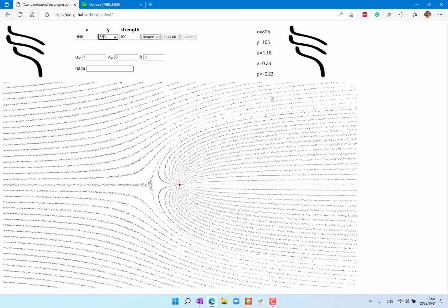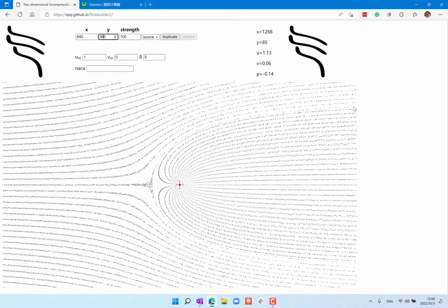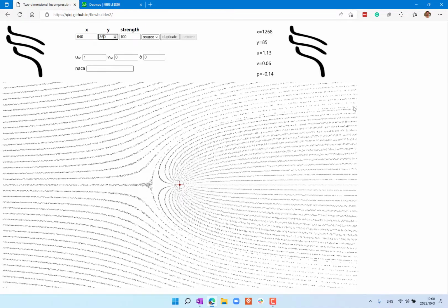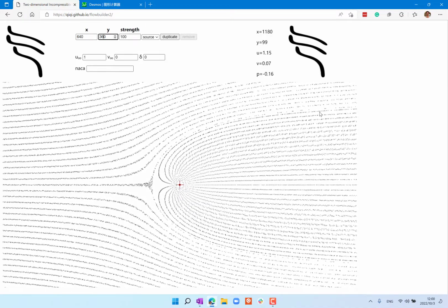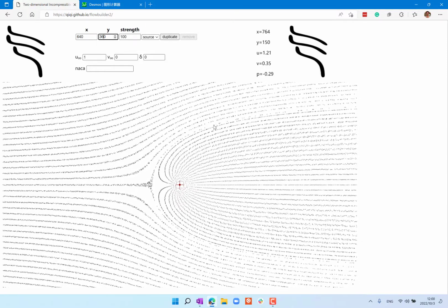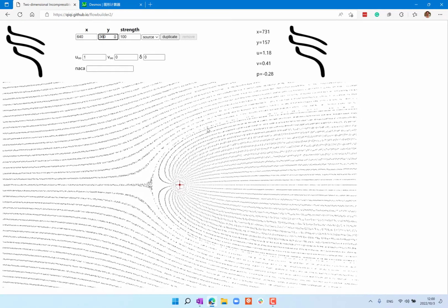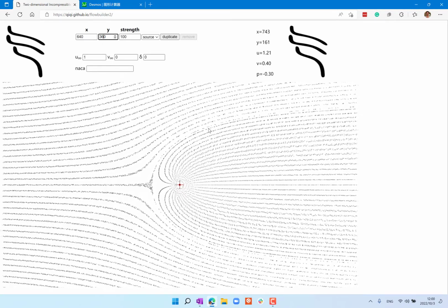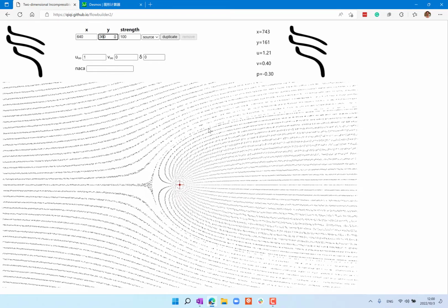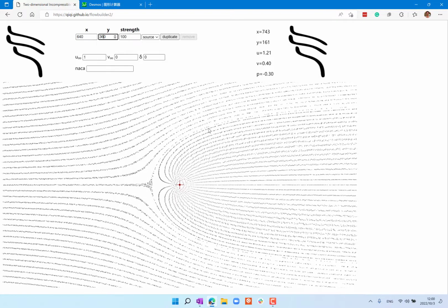And then as you go more downward, the pressure kind of recovers. It's still negative, but starts to get closer to zero, right? At some point, you get a minimum of pressure, maximum suction, like over here. So that's how the flow field is around the leading edge of a symmetric airfoil.